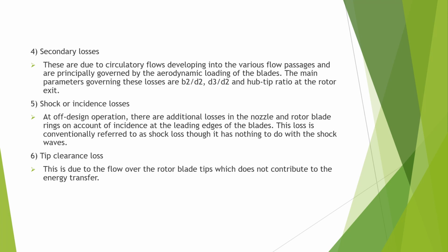Shock or incidence losses. At off-design operation, there are additional losses in the nozzle and rotor blade rings on account of incidence at the leading edge of the blades. This loss is conventionally referred to as a shock loss, though it has nothing to do with shock waves. And the last one is tip clearance loss. This is due to the flow over the rotor blade tips, which does not contribute to the energy transfer.